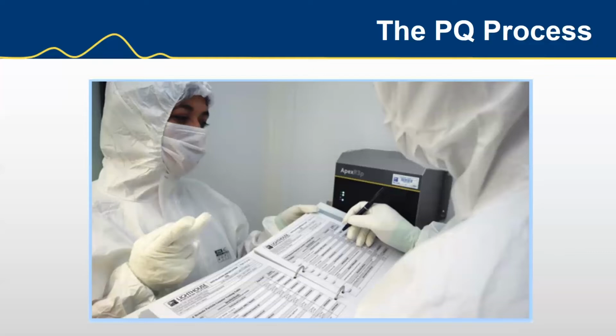During the IQ/OQ, which is normally conducted by the vendor, in most cases with the customer as a witness, depending on the customer's availability. Again, it is not required in regulatory. The IQ/OQ will test that the system is running, but the performance qualification really needs to, as I say, shake the tree and test the weaknesses. It should be seen as an opportunity for the customer, end users and managers to fully understand the system. It's kind of like taking a car for a test drive.